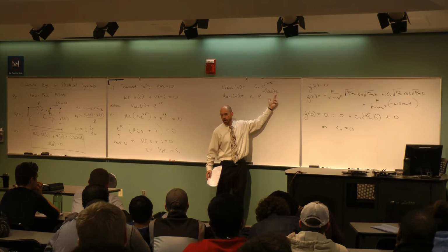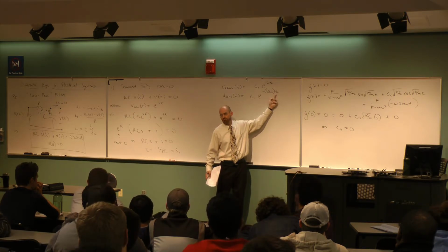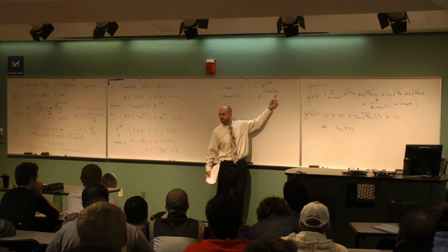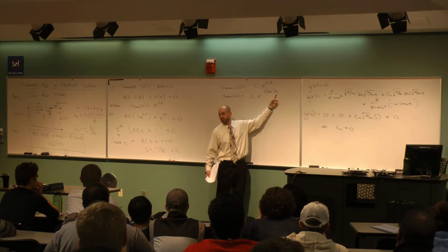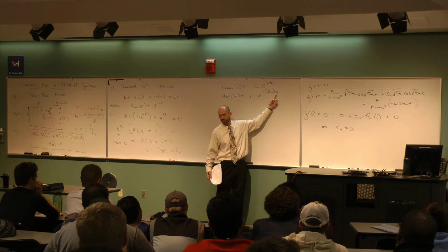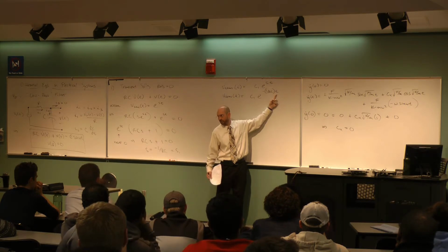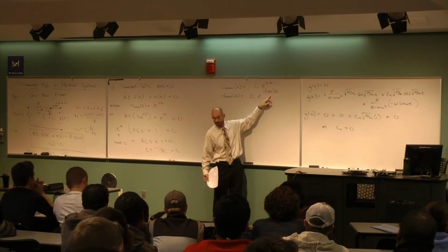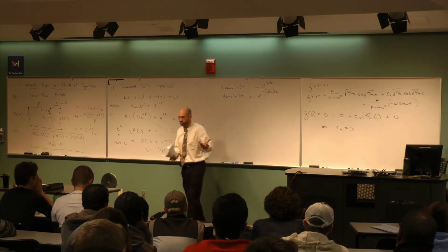How fast do I go? Multiples of what? Multiples of t. Multiples of R times C, right? When t equals RC, this is e to the minus 1. When t equals 2RC, it's e to the minus 2. When t equals 3RC, it's e to the minus 3. RC is the time constant here. Right? So does this happen fast or slow?